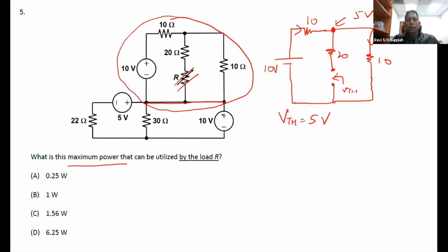Okay, so the plus connected to negative is this plus, that means the positive of the supply here connected to the negative of another supply here. That means you consider that this can be treated like a common point where the 2 circuits can be separated. Okay, you can think of it like a common ground where you separate out circuits, and you can analyze them separately.